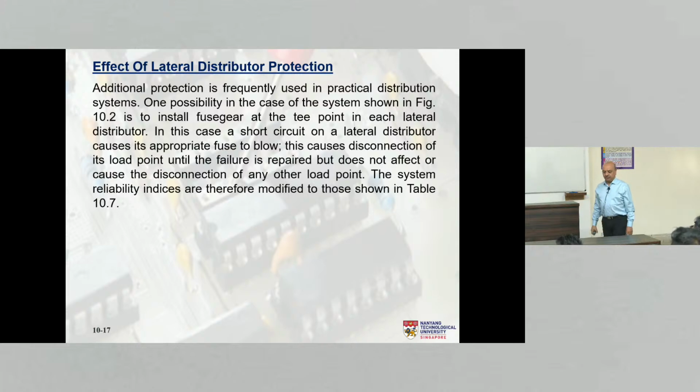Right, so we have seen a very simple configuration, only one breaker. Whenever there is a fault on any main section or lateral distributor, the breaker operates, and therefore we lose power at all the load points. Not the best system to have.